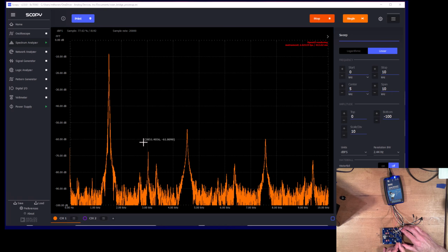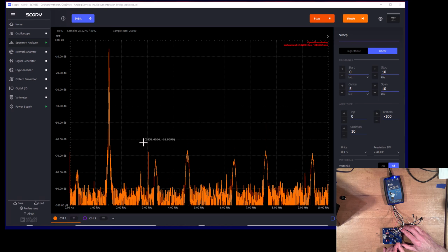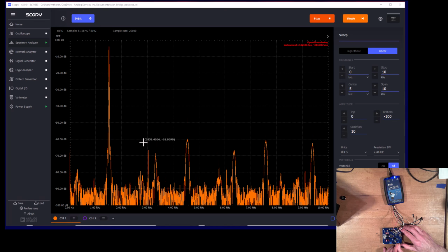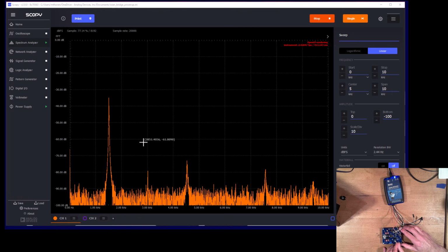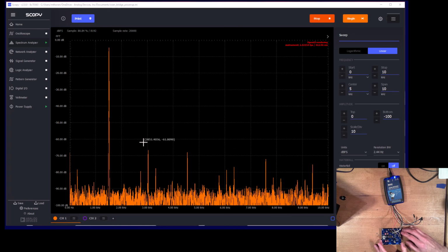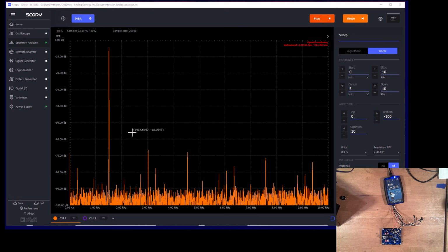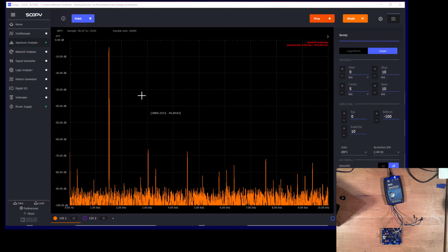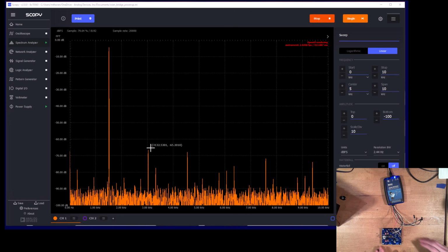And then let's back the gain off a little bit. Okay, a little bit more. Okay, yeah, and so let's see what we have here. So 10, 20, 30, 40, 50, at least 60 dB. So we're at about 0.1% distortion, so at least 10 times better.